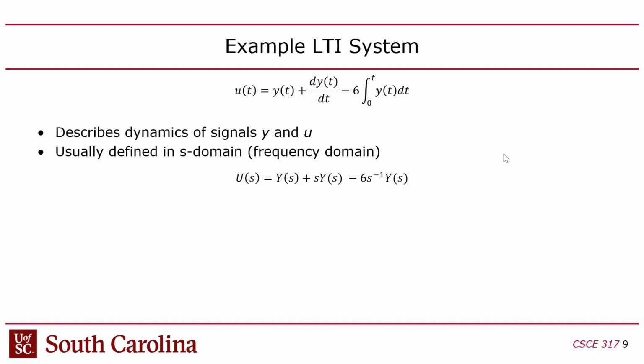And normally, to simplify this, you would represent this in the S domain, the Laplace domain. And this is pretty simple to do because if you have, for example, U of t, the Laplace of that is just U of S, right? But it's usually capitalized U. If you have the derivative of a signal, so in this case, the derivative of Y with respect to t is just rewritten in the Laplace domain as having a coefficient of S, S capital Y of S.